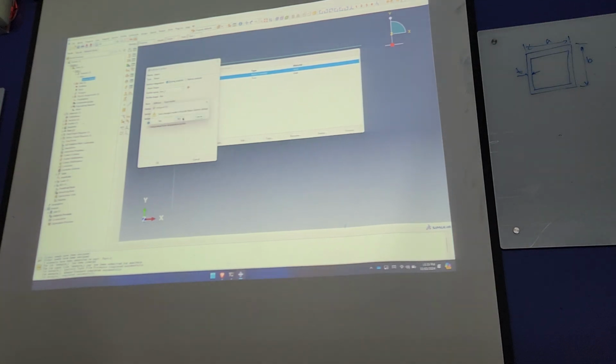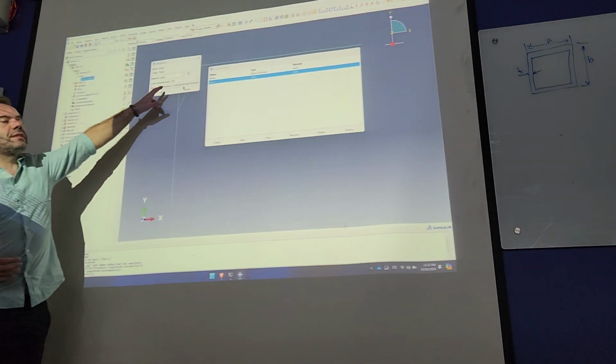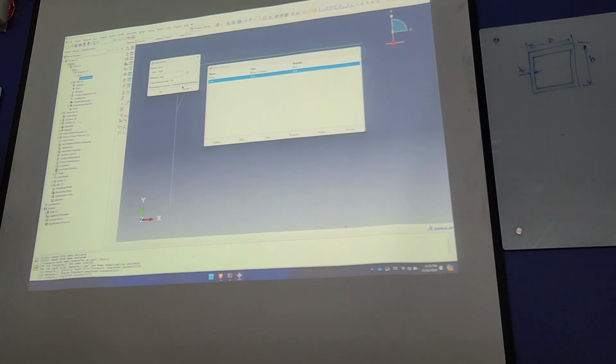When it comes to truss, we don't have that requirement. It only asks for the actual amount of cross-sectional area. Why? Because a truss does not bend. It only gets stretched or compressed. It gets longer or shorter. It cannot bend. Therefore, profile is not of interest.